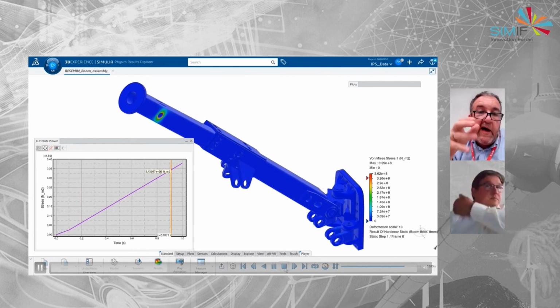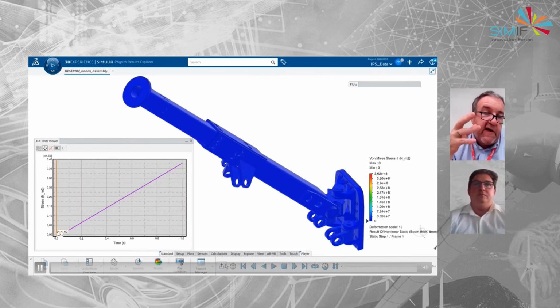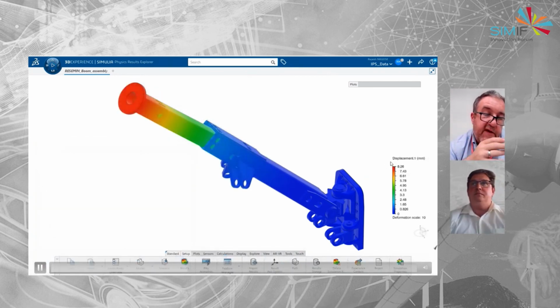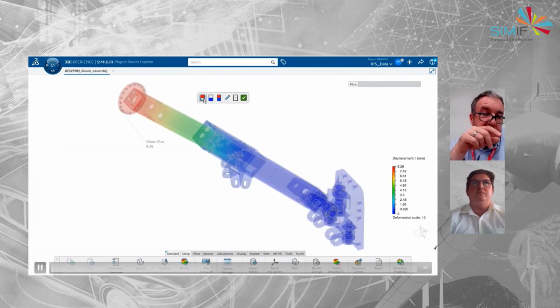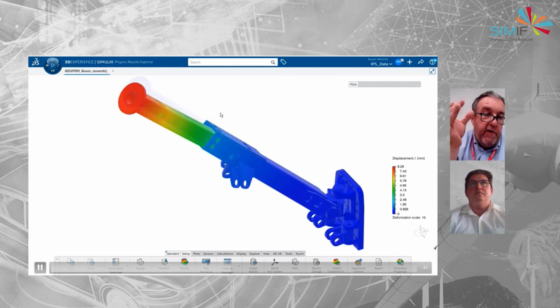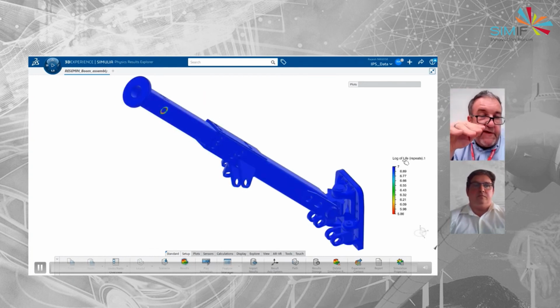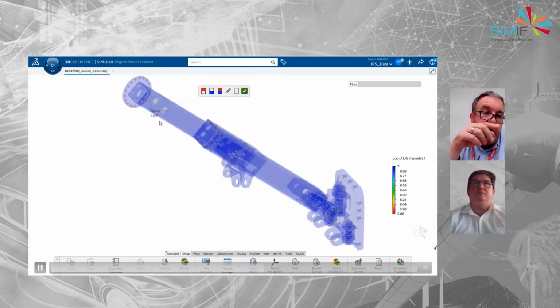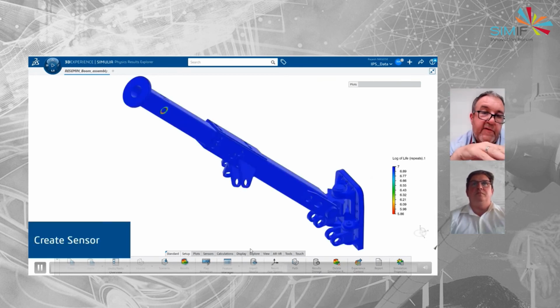So I can start making judgments or advice to Andy to pass back to him, to say, can you consider increasing the wall thickness in this particular area because it's going to come under quite a bit of stress, and certain areas based upon the fatigue might be under a lot of stress in there. So we can analyze the data and get that fed back to him very quickly to make those changes.